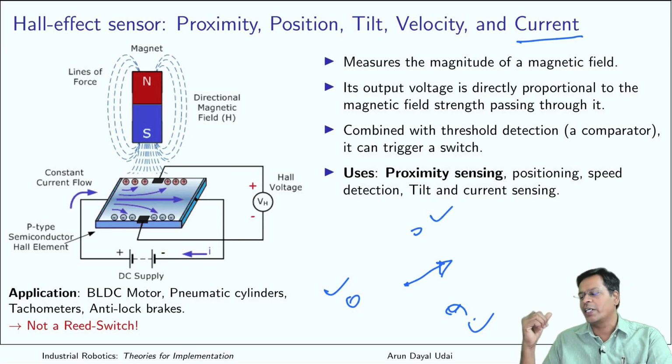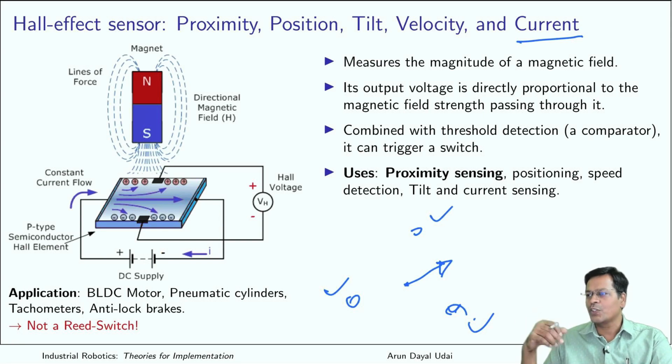But there is a drawback. It has to be isolated. There should not be any external magnetic field apart from the magnetic field that you want to detect. So you have to shield it thoroughly and leave just one window open where you are expecting your signal to get in.